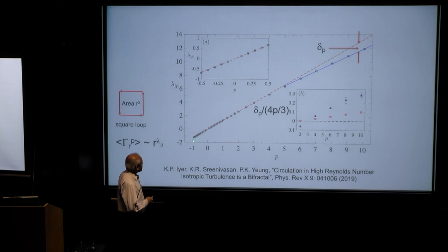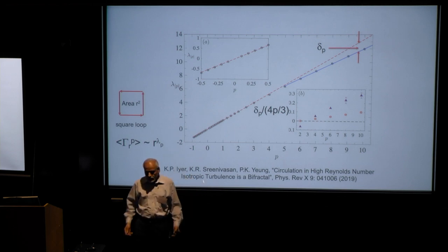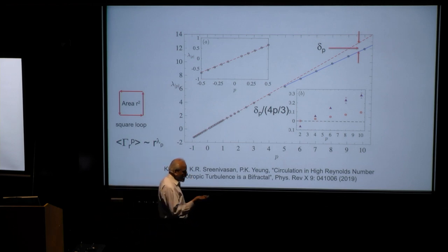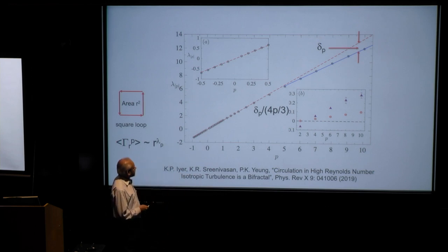What you find is, unlike the case for structure functions and so on, which depart from this Kolmogorov line substantially and nonlinearly, which is the multifractal characteristic, which is what makes the problem very difficult. That is to say, if you know one exponent, you can't rightly extrapolate to another exponent, etc. What you find is for low order moments, it's almost Kolmogorov.